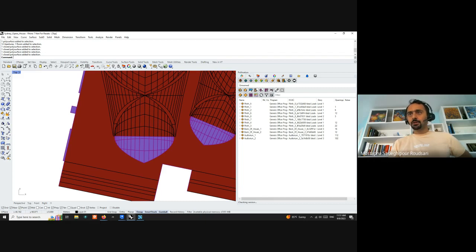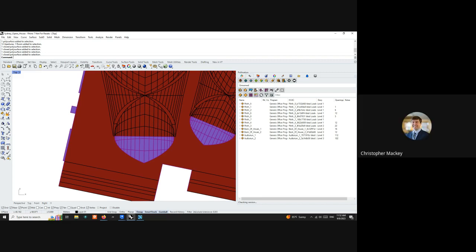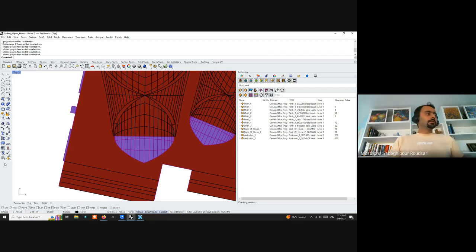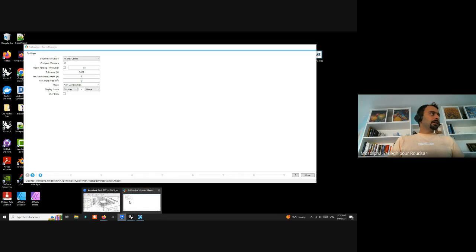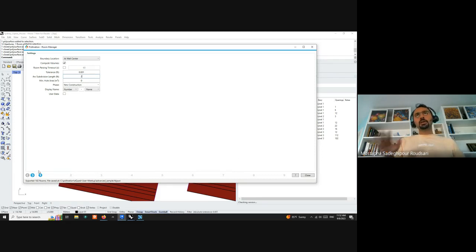PO merge rooms, I already showed that. I think Abdul's question got lost in the mix. He was just asking, using Revit, can we export to GBXML? Yes, you can. The challenge with GBXML is that we export a clean GBXML if your model is clean, but depending on the software you use to import it, it may or may not go through well. We cannot guarantee other software to deal with GBXML correctly. That's the limitation. But can you export to GBXML? Yes, you absolutely can.